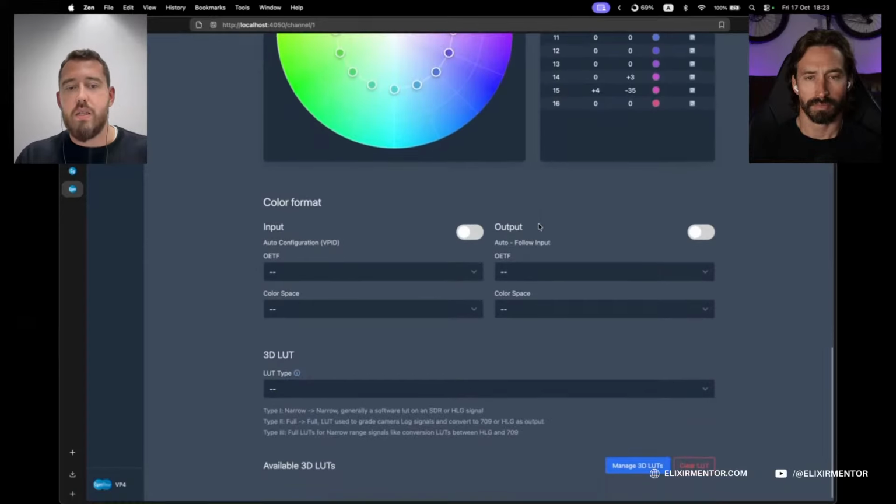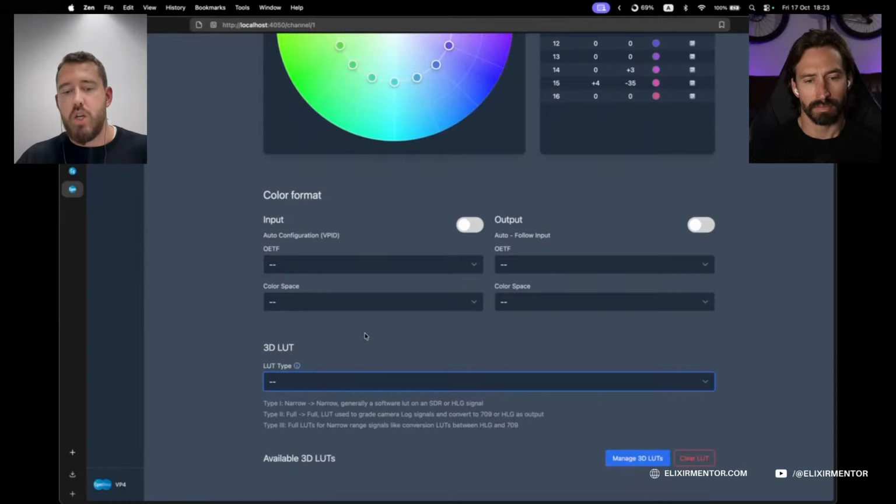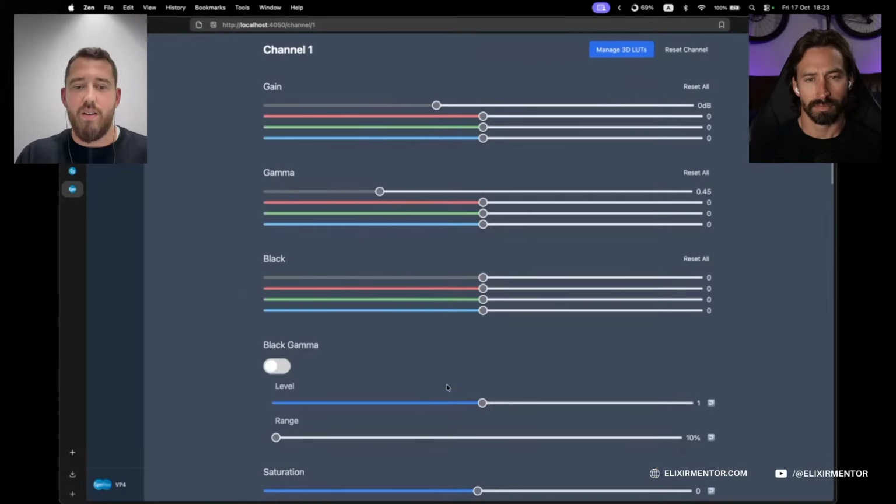And since it's a color corrector box, we have the 3D LUT files. You apply the precompiled 3D LUT files to the FPGA, which is running on the device. That's how you do the color correction and color shading without delays.